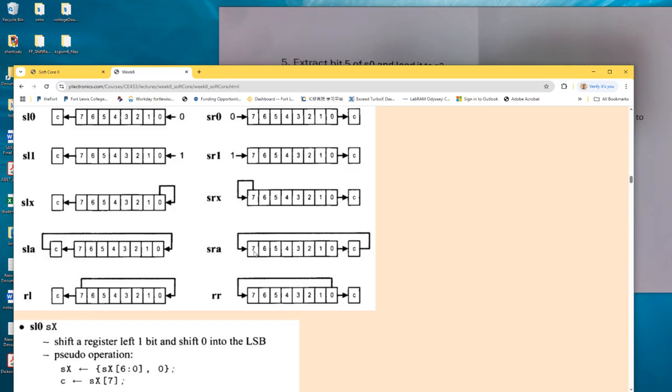And where's the LSB? It's in C, okay? However, you do need that LSB to go to the lower byte. So then we use SRA. So what is the current C now? The LSB of the first one, right? Okay. However, the SRA is also shifting the LSB to C. So the C will be updated, but does that matter?